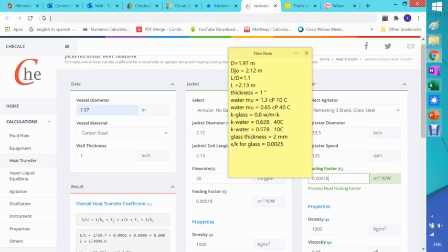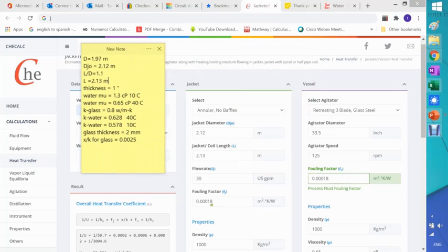Let's talk a little bit about this. Fouling in a glass lined reactor will be 0. I mean, you clean the vessel and you go back to the original basis. So it shouldn't be a problem. Now, at the jacket side, the jacket will be another story here. As the jacket is being used, more accumulation starts to get there, and that would be a problem in the long run. So you need some time to do a shutdown and clean those jackets properly.